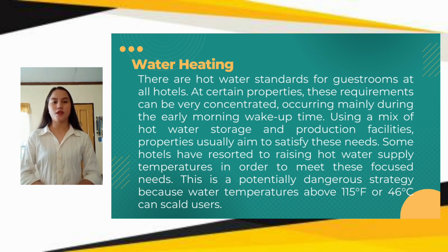There are hot water standards for guest rooms at all hotels. At certain properties, these requirements can be very concentrated, occurring mainly during the early morning wake up time. Using a mix of hot water storage and production facilities, properties usually aim to satisfy these needs. Some hotels have resorted to raising hot water supply temperatures in order to meet these focused needs. This is a potentially dangerous strategy because water temperatures above 115 degrees Fahrenheit or 40 Celsius can scald users.